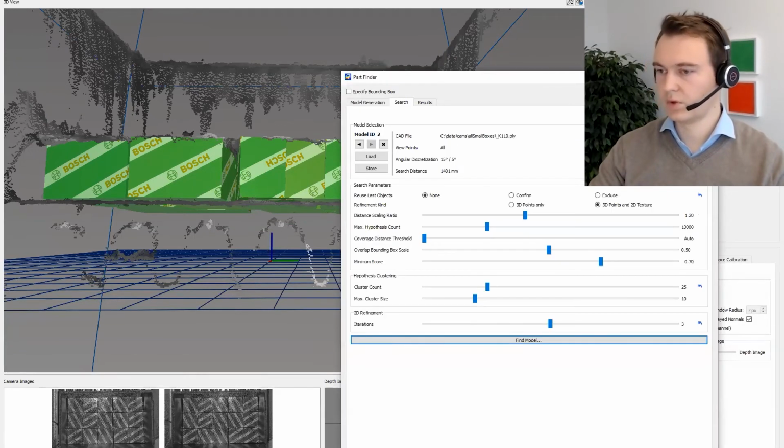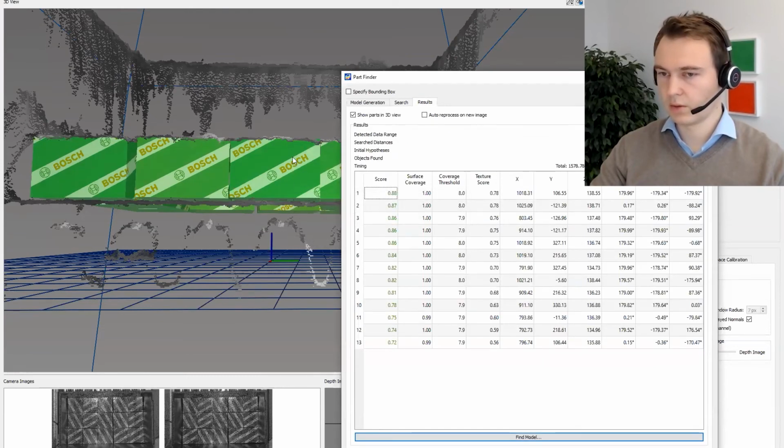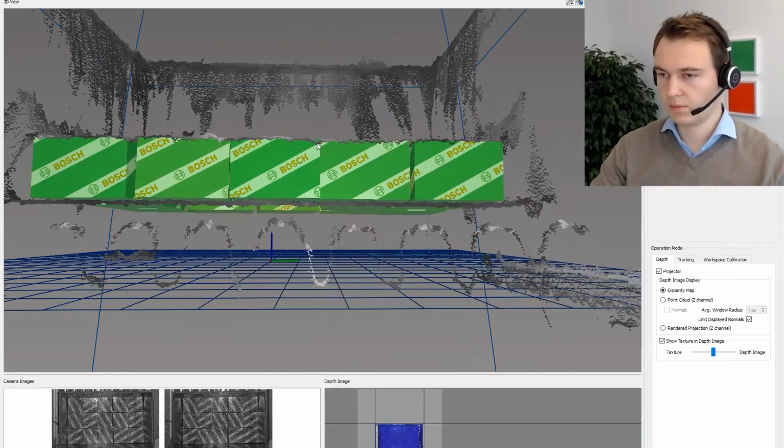Okay, so I have to take the advanced box here, and here are the overlap sliders. So you can basically tell it to not allow any overlap or just a little bit. So we want to have the full object not colliding with anything else, or at least we allow maybe 5% of collision. And maybe we just click again. So now the colliding objects in between are gone, you see.